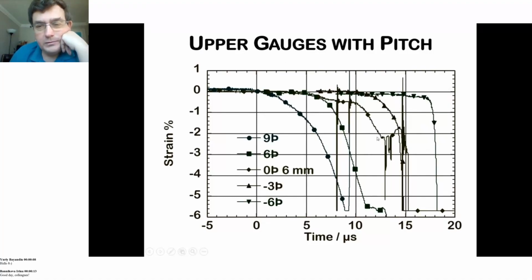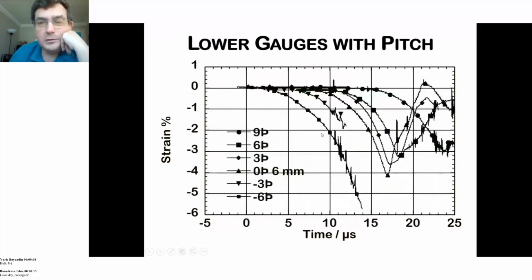On these ones, you'll see this peak more clearly. So this is showing that there is some flexing of the rod during impact. So the rod bends and then kind of recovers back to a linear rod without any bend in it before the full penetration occurs. So there's some flexing on the rod as well that you are detecting.